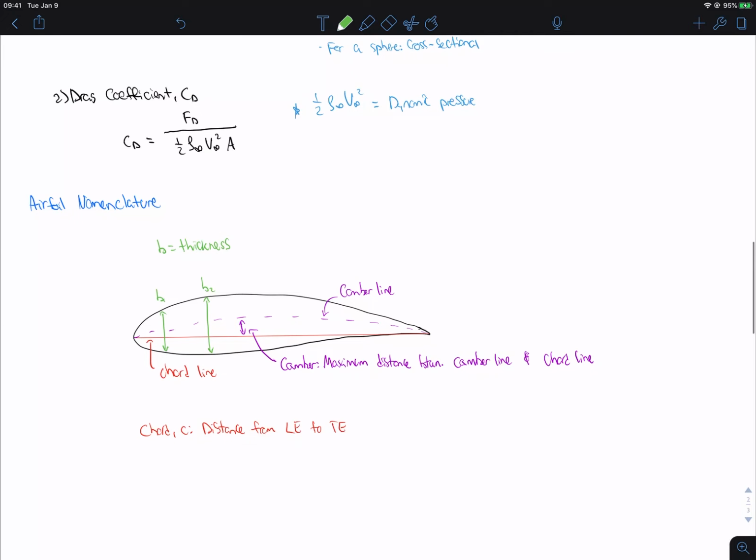Okay, so as we discussed earlier, one of the things we need to find before we can find the drag and lift coefficient is the local airspeed. Again, this is going to be pretty similar to what we did in lab 2. In lab 2, we used a pitot tube and a manometer to measure the local airspeed. The pitot tube measured the stagnation pressure, and then we had a static port on the side of our air duct that went to a manometer. We combined those two things to have our stagnation pressure and our static pressure, and then we could find the local airspeed in the duct.